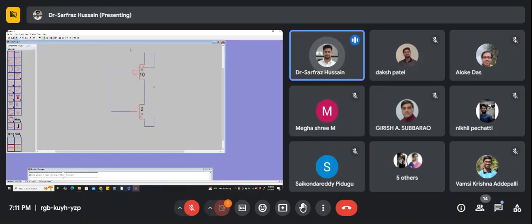Okay, so here I need to give some pin numbers also. Now before that one, for the NMOS, I have not chosen a size. So I'll single click on NMOS. I'll press Control and I, and here in the width, I'll write it as 5, and length also I'll write it as 5. So 5 means 1 micro. So I've kept NMOS as 1 micro, 1 micro, and the PMOS as 2 micro and 1 micro. So you can also do this. If you go to this MIS, you can actually put some text, right? So annotation text and all those things you can put here. If you want to put some text here to represent something, that also you can put using this miscellaneous.